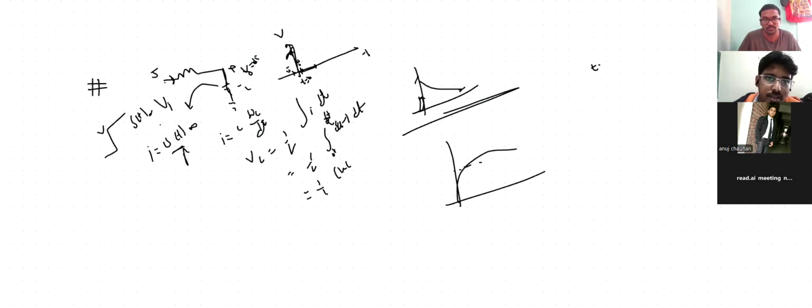Here, what I feel, sir, is that in the impulse condition, the ideal property of a capacitor is that it holds the voltage. So comparing the t equal to 0 and t equal to 0 plus conditions, in both cases it should be the same for a capacitor, VC of 0. But in this case, due to the impulse, VC at 0 and at 0 plus is different, sir.